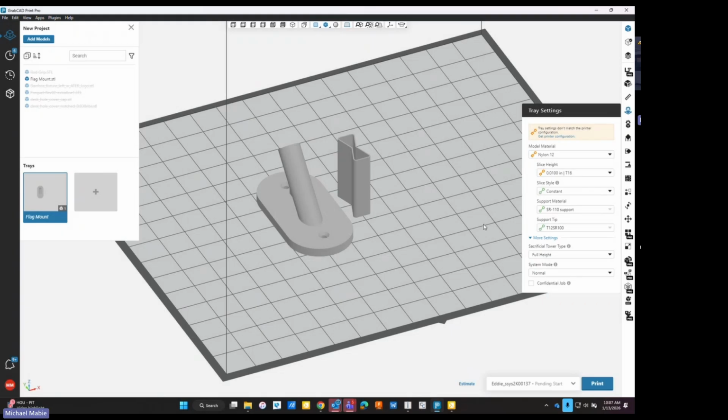Now, one thing to keep in mind, this is a per build setting because we're changing the entire envelope temp. And so if I have, say, a thin wall part and a really thick part, it might not be a very good idea to run those together because you're going to have one that's either going to curl or one that's going to warp and distort.